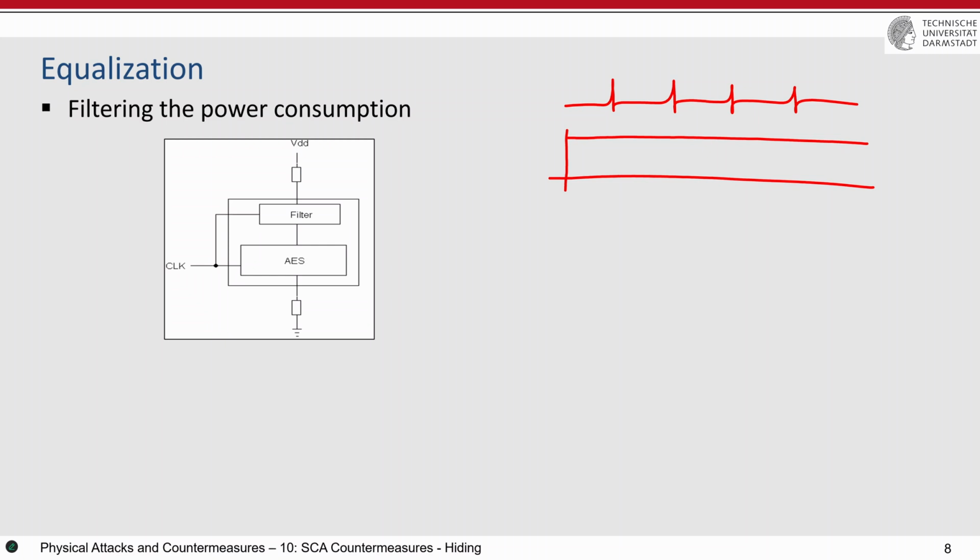Why? Because if you remember, we discussed the dynamic power consumption of CMOS circuits. If your filter works like this, then the amount of power consumption or the energy consumption is constant, so it doesn't matter if the device works or doesn't work, a very high amount of current is consumed. You know, if the device is battery operated, the battery will be over very, very early and soon.